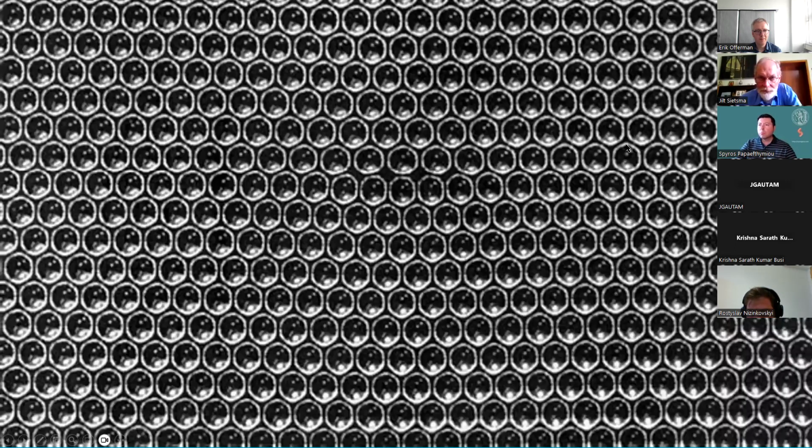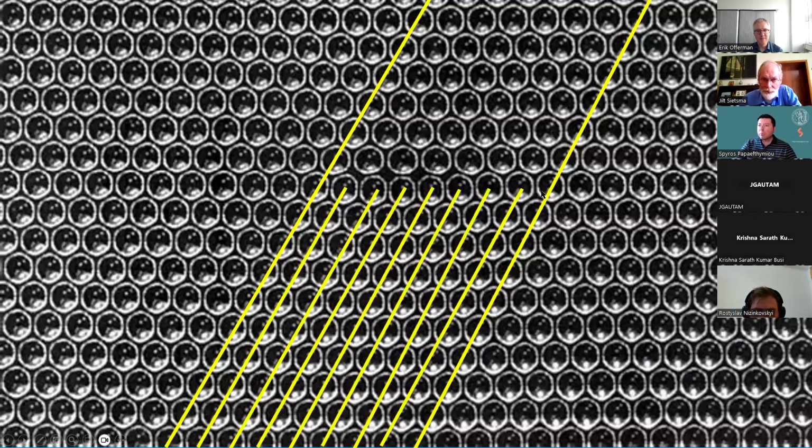Well, you all know what a dislocation is. Do you see the dislocation here? This is a closely packed plane, and you see that something's wrong here in the middle. Hopefully you see my mouse. If you look at the character of the dislocation, these are crystallographic planes, perfect planes. If you look in between these two lines, you see 7 planes on the bottom side and 6 planes on the top side of the dislocation. So that is what we call an edge dislocation with an extra half plane on the bottom side in this case. They occur at random.